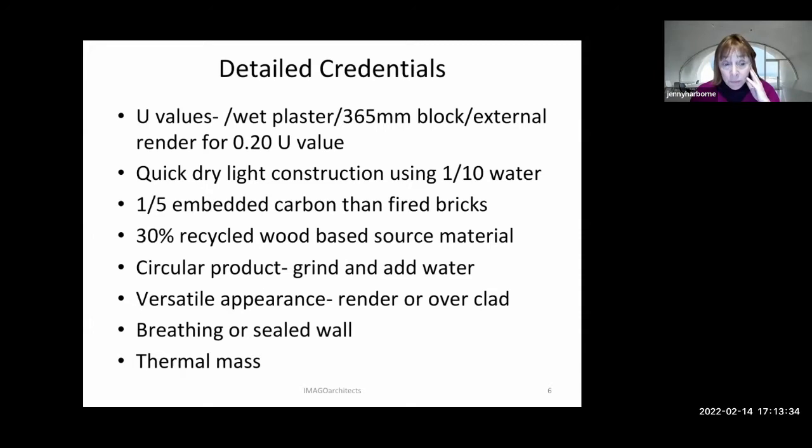The actual blocks have about a fifth of the embedded carbon of an ordinary fired brick. So that's really quite impressive, because they don't have to be fired at such a high temperature. They mix 30% of the product as a recycled wood-based material in with the clay to fire it. And it's a really circular product. If there's any waste, or if you were to demolish a clay block wall or something, it's just ground down and then you just add water and start again, fire it up. So it's amazing.